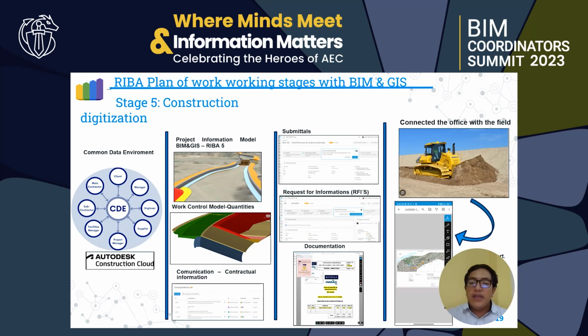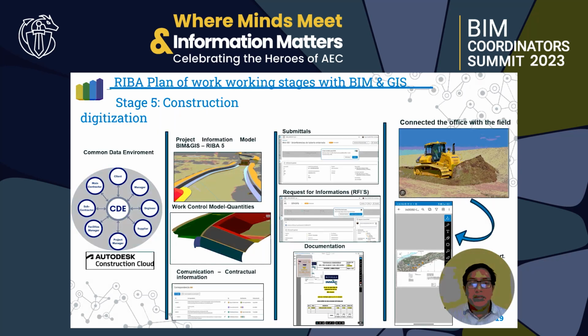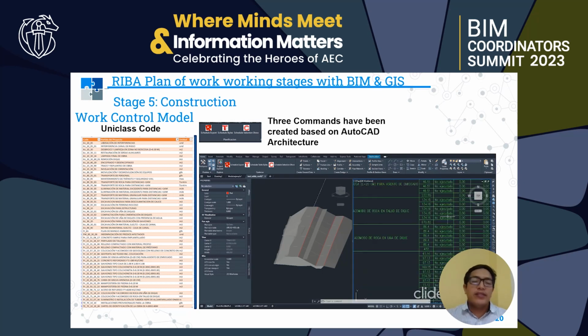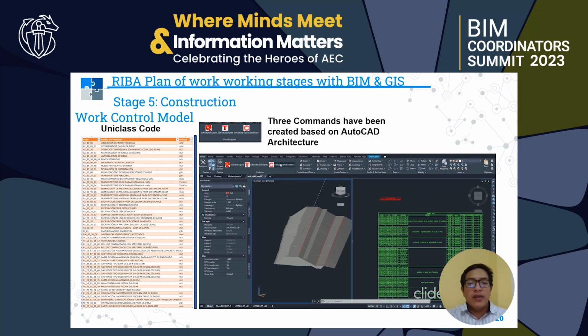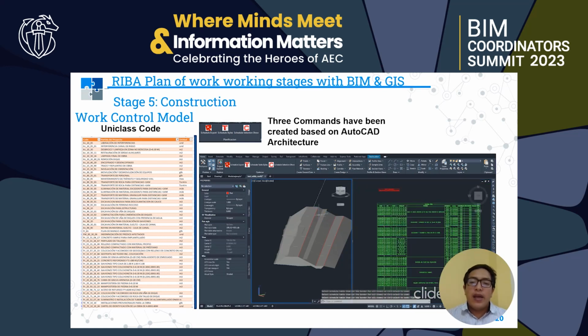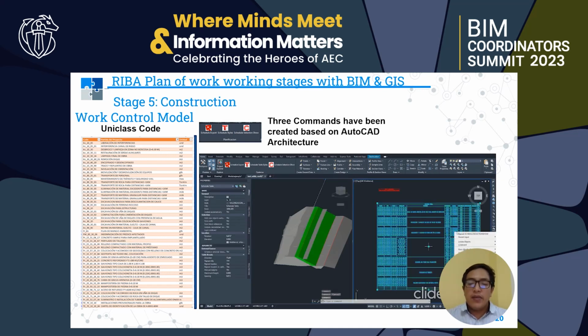Safety and health formats in the work. Likewise, the control of the quantities is validated through the BIM model. The BIM models that are created with Civil 3D have the Uniclass 2015 classification system coded to the asset models. Thus, they are also linked to the activity to build these assets.